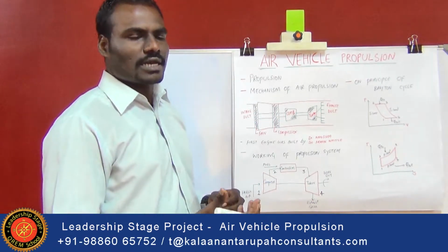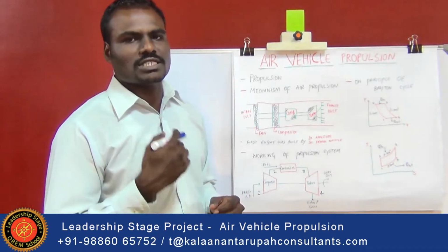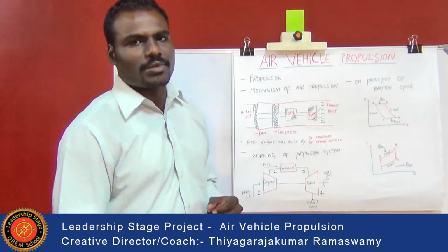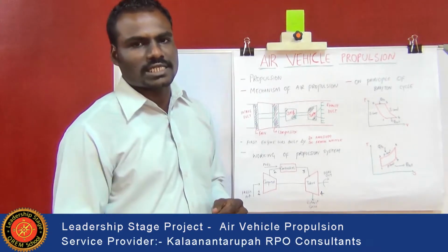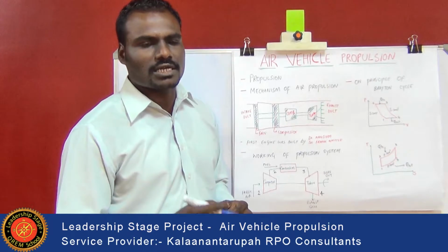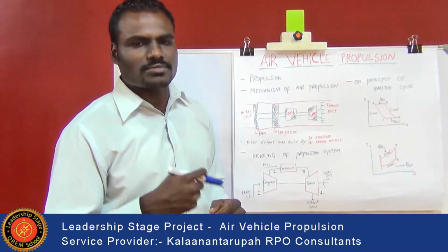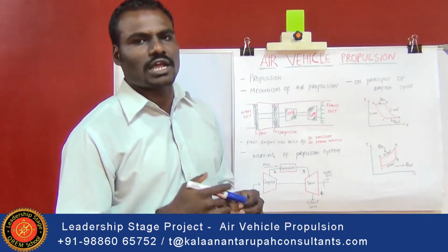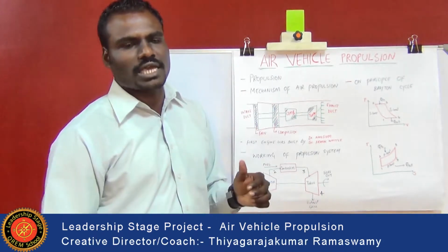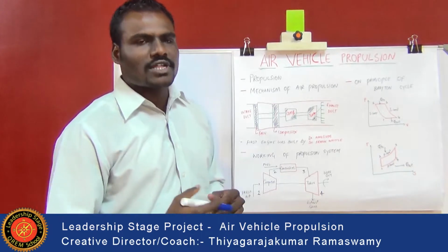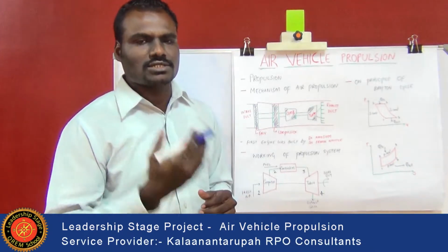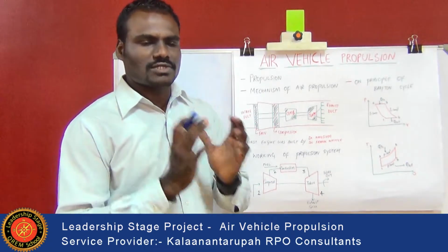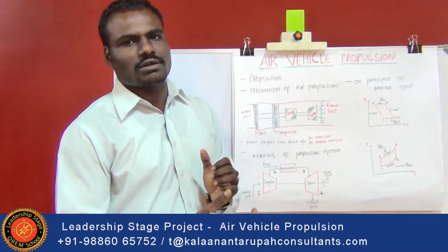The power developed in the combustion chamber is passed to the turbine, where the pressure is reduced, and the exhaust gases released from the combustion chamber leave the turbine at a higher velocity, so that the expansion process is carried out in the turbine. After the turbine the exhaust gas reaches the nozzle structure, which is a convergent or divergent nozzle.